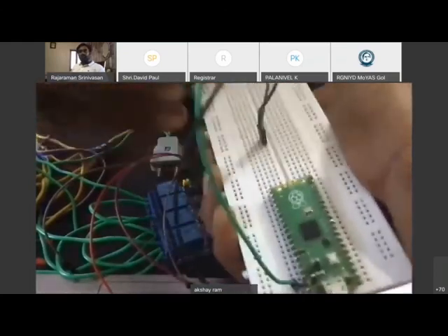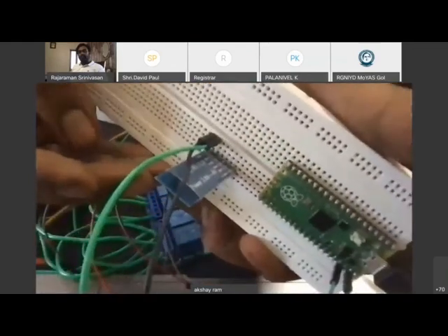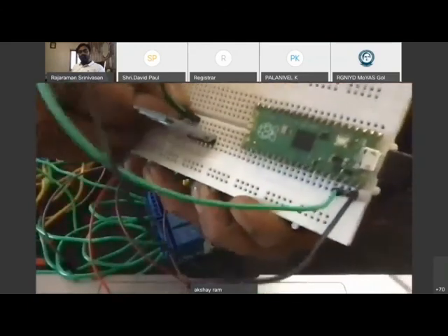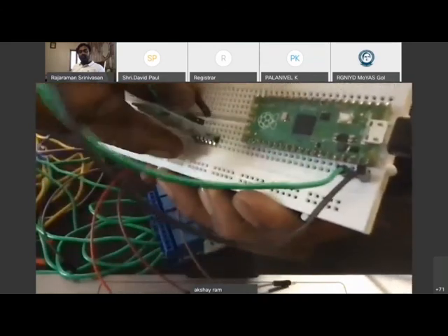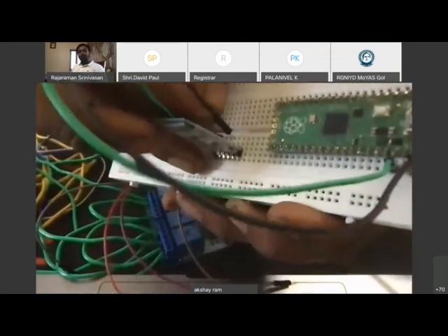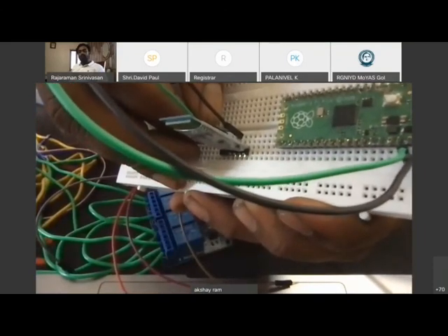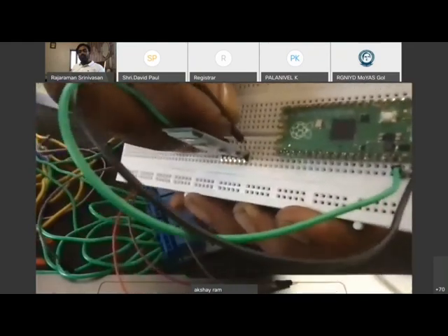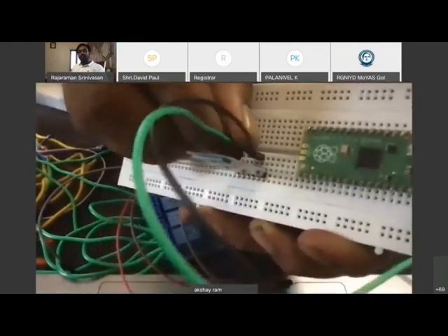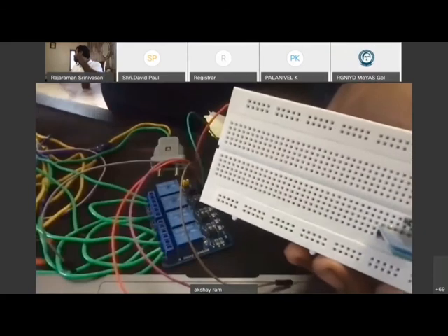So now there is power. Power is coming to the Bluetooth. To make it easier, you can just plug it this way. Then you could see what pin is what. So VCC has come this side. So this goes to VCC. This goes to ground, green color. Black goes to VCC and green comes to ground. So now we have to just use the TX, RX pins.